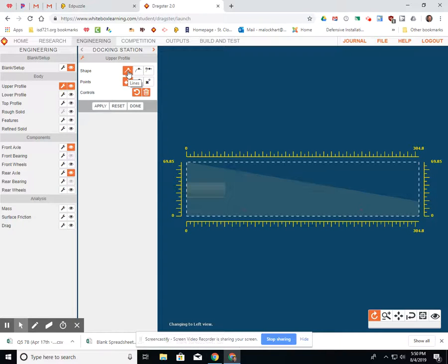We have a line tool, we have a spline tool, and we have a curves tool. I'm going to show you all 3 in this video. However, my suggestion is do not use the curves until you have a very good knowledge of the first 2 beforehand, because the curves tool will basically get you really complicated designs. We'll talk about that when I show it to you in a little bit, and you'll see why.